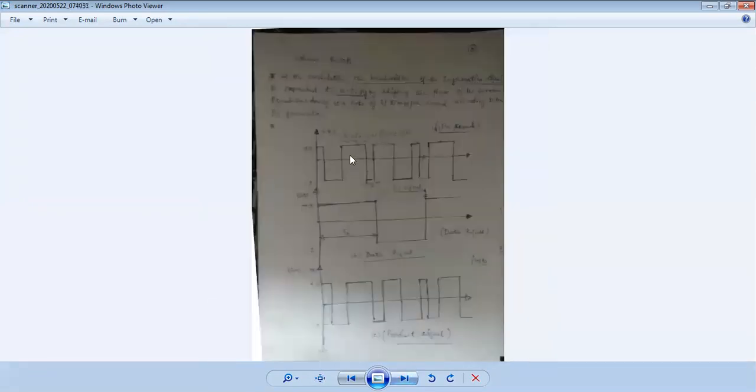Now look back at how I mentioned it. Let us take the PN signal generator. It has a number of bits per cycle, and this is the data to be transferred. The number of bit cycles is small, so the bandwidth used is quite low. Now I need to increase the bandwidth of the signal. As simple as this, just multiply V(t) and C(t). I'll get back to this equation. So the number of cycles per second, that is the frequency, has been increased. If it's a high frequency, a high data rate has been achieved.